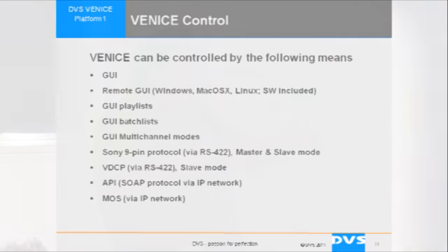We support the classical, as mentioned before, Sony 9-pin protocol via RS422, master-slave. We support VDCP fully via RS422 or via SOAP. We have a complete API that is defined, so any function inside the box can be reached externally via SOAP commands. And that is very helpful to migrate into different applications. So whatever it is, a quality assurance application like the Baton one we have seen here could be easily migrated, the migration to a new system, and so on, because it's all SOAP-based.